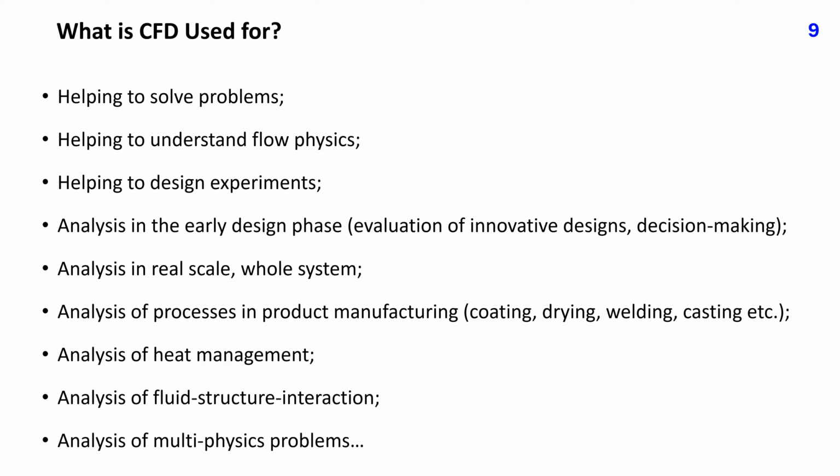Flow visualization, detection of flow unsteadiness, vortex shedding, zones of flow cooling, and so on, help engineers to detect the cause of the problem. Knowing the cause usually leads to ideas for problem solution. Simulation can also confirm whether the ideas work or not. CFD helps to understand the physics of the flow. It is especially important if one wants to improve the design, introduce the measures to avoid possible problems, for example heat shielding to prevent overheating of critical components, measures to suppress possible unsteadiness or vortex shedding, etc.